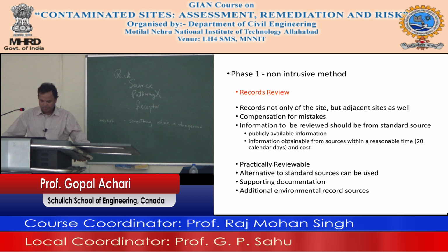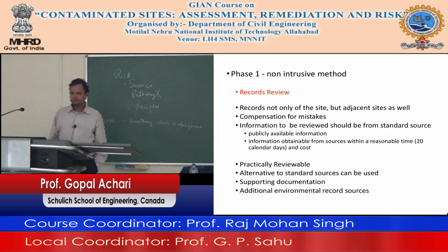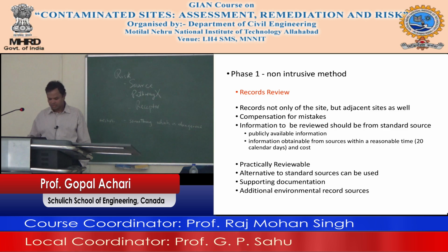Supporting documents should be a part of the report. Additional environmental record sources should be reasonably ascertainable, or in a reasonable time it's accessible and sufficiently useful. A geographical survey 2.5 minute topographical map is very useful. Should look at groundwater maps, bedrock geology maps, surficial geology maps, soil maps.